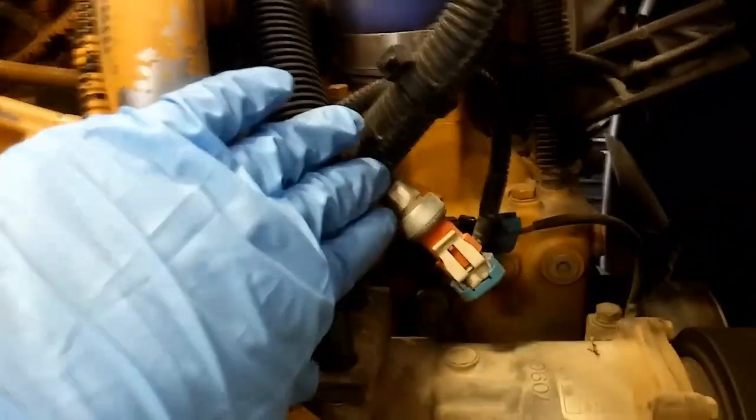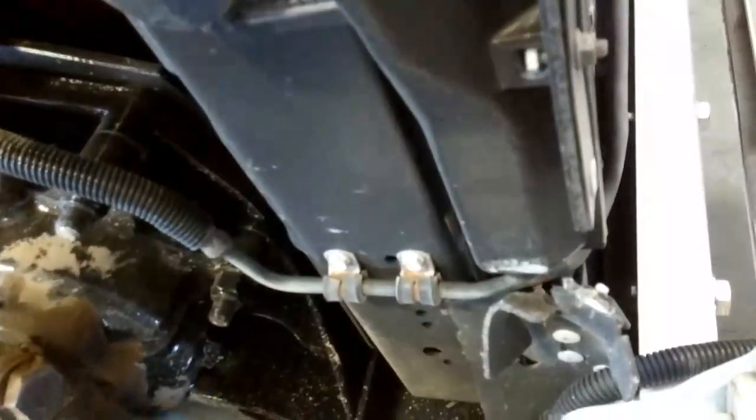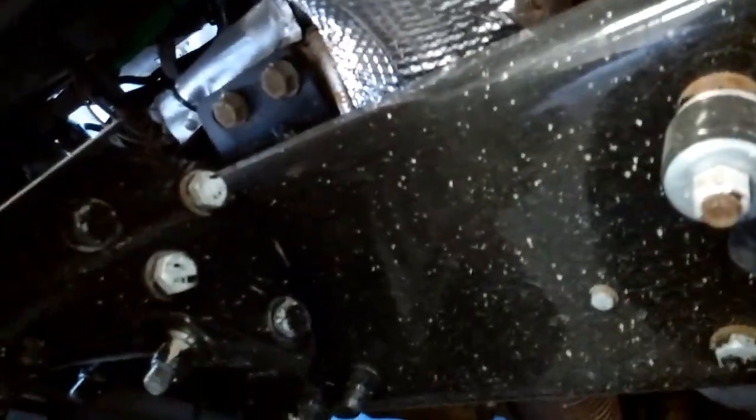Now the first thing I do whenever the AC is not blowing cold is a visual inspection. This is before I hook up gauges or anything. Is the serpentine belt there? I'm going to look at all the lines. I'm going to look at the condenser. Is the condenser damaged? And also what you're looking for is oil spots, but more particularly anywhere where dirt is sticking on any of the AC lines or any of the AC components.